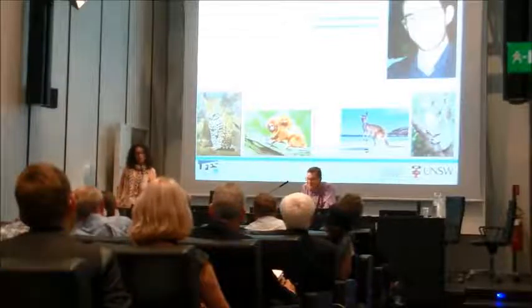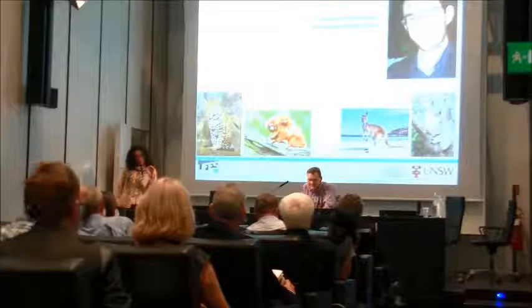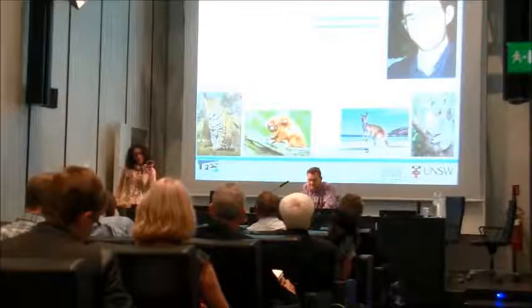Yeah, just to point out that actually the most important parameter is not the velocity itself, but the friction velocity. That's what we have to calculate and be sure of inside the wind tunnel, so as to simulate the atmosphere.